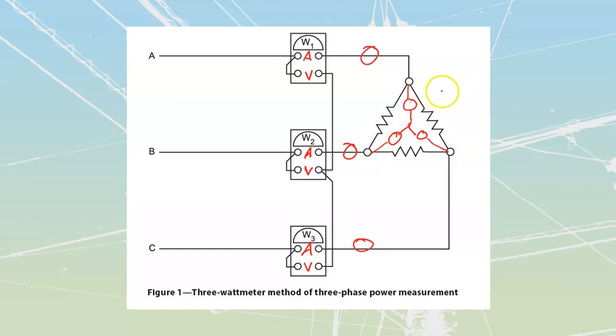It's as if our voltmeter sections were all placed across the center and as if our ammeter sections were placed in line. These are those voltmeter sections. We see we're measuring the volts from the line over to a central star point. Across that one, we're going from the line to that central star on this one, and from the line over to that central star on this one here as well.